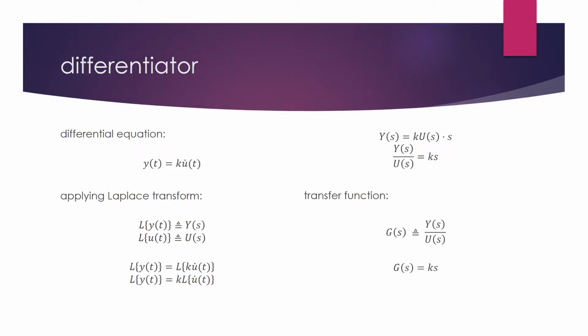The differentiator is substantially a high-pass filter. It can generate a square wave with alternating direction voltage spikes when a square wave is applied. In ideal cases, a differentiator will reverse the effect of an integrator on a waveform, and vice versa. Hence, they are most commonly used in wave shaping circuits to detect high-frequency components in an input signal.